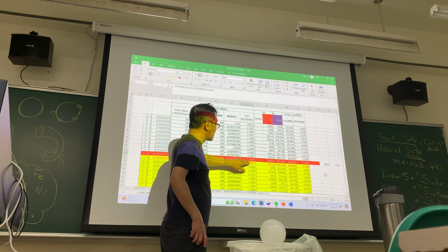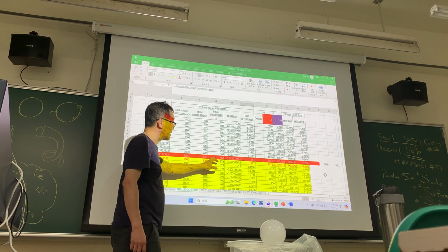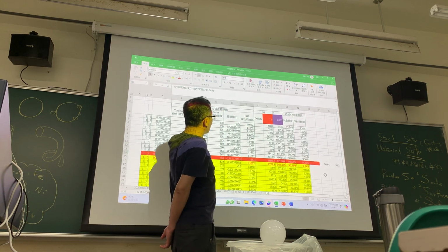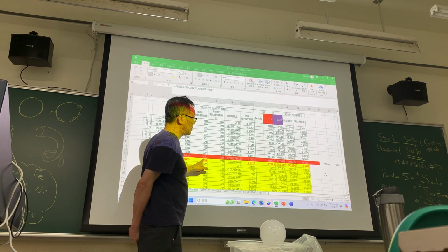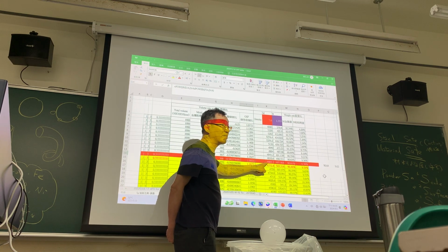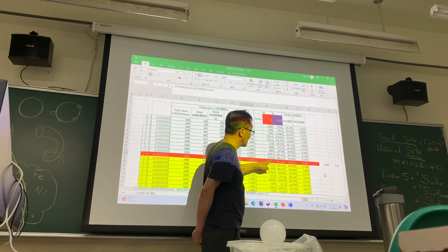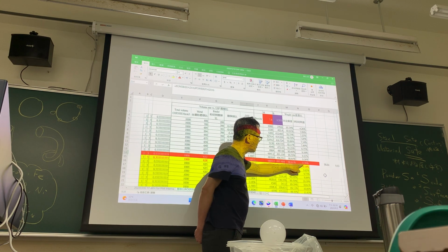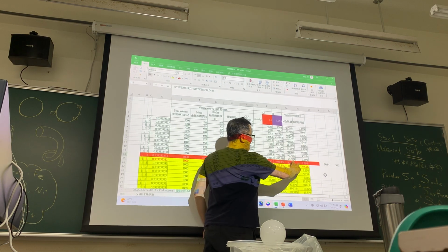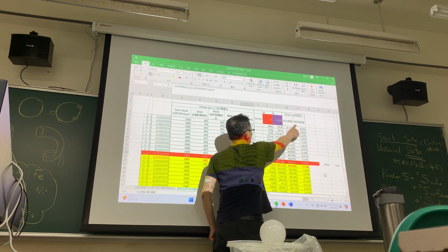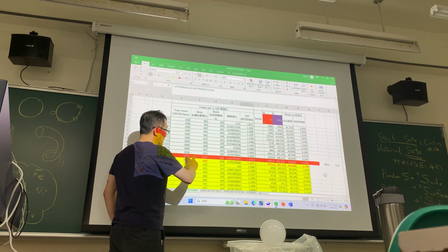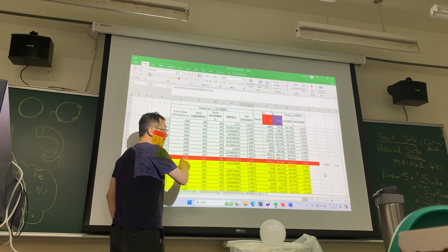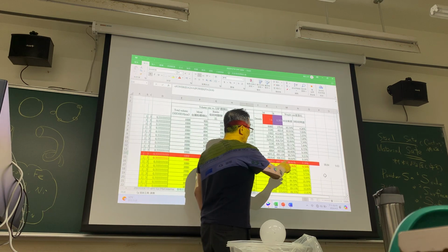Then after we got this one, we know the volume, then we can switch back because here is density. So this is the metal density. We know the metal density and the volume, so we can know the weight percent. Then we can know the weight percent of metal and the weight percent of iron. Then this one is 90.1, 9.31 weight percent. So these are the weight percents of the metal and the binder, and this one is the total. Okay, so we can use this to make measurements to check.